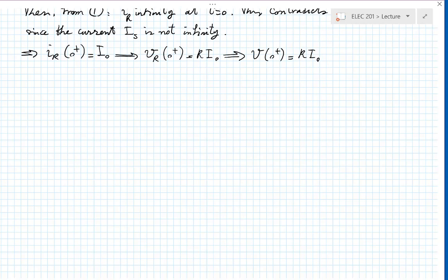But if it didn't have any of these things, and it tried to change very rapidly, now it's not going to be instantaneously changing, but it's going to be very rapid. So your voltage is not going to be infinity. The slope of that change is not going to be infinity, but it's going to be very, very large. So you will have momentarily a very large voltage drop across the inductor. And that could end up frying something in the current source, could lead to maybe a small arc somewhere in the air. And it could potentially have catastrophic consequences. Fire, it's a hazardous thing. Okay.